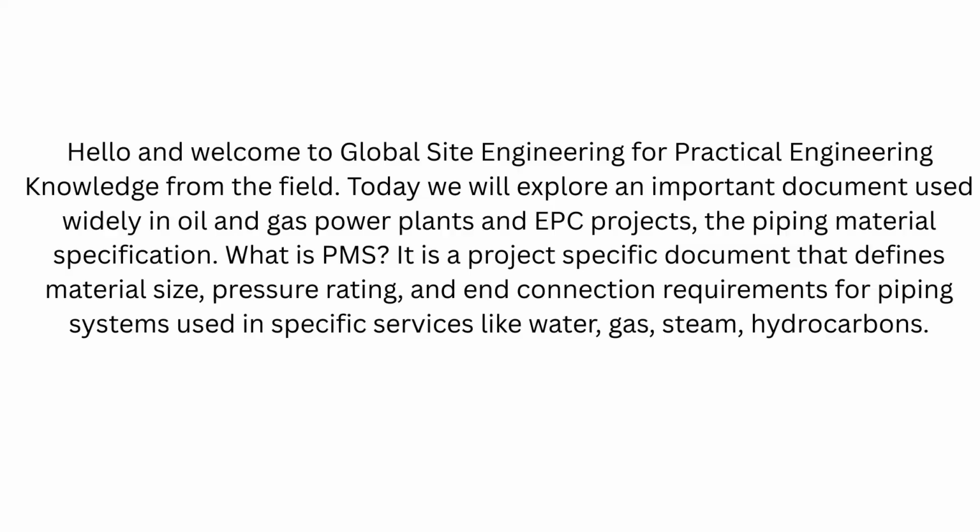Today we will explore an important document used widely in oil and gas, power plants, and EPC projects: the Piping Material Specification. What is PMS? It is a project-specific document that defines material, size, pressure rating, and end connection requirements for piping systems used in specific services like water, gas, steam, hydrocarbons.